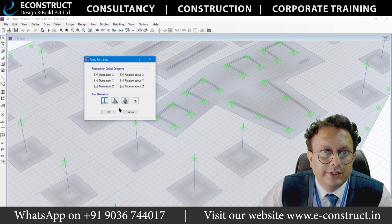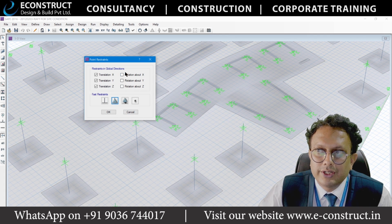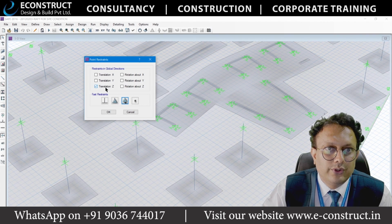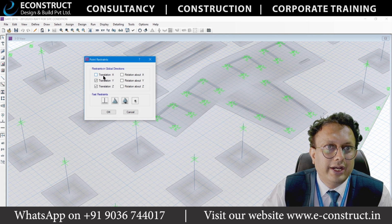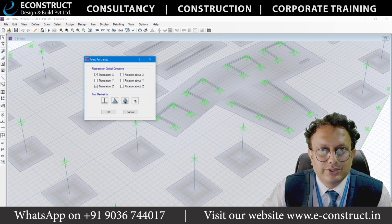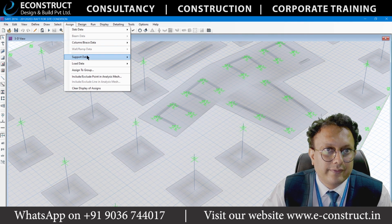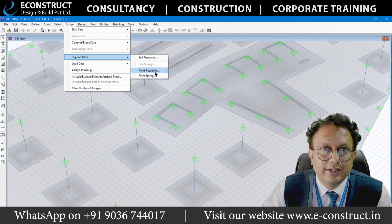Yes. You can, if you see this rotation will be 0, means it is allowed to rotate. This is a roller, means only FZ, in only one direction, where it is allowed in X direction. This is like a railway line going in this direction. This is in Y direction, so it is allowed to go in the Y direction. So these are the point restraints. Now similarly, if you go here, these are point restraints.